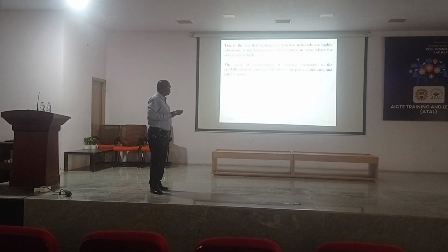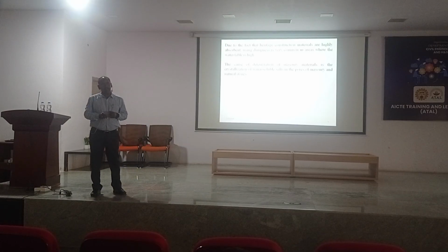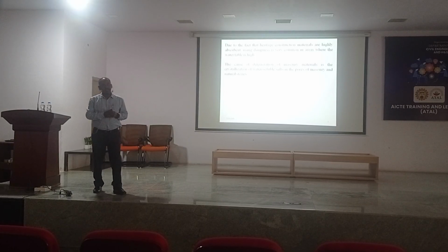The cause of deterioration of masonry materials is the crystallization of water soluble salts. Water soluble means, if you take chloride, it is water soluble and it enters the pores of the mortar, then it will create problems. The mortar is subjected to cracks.